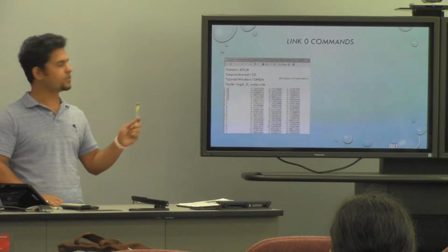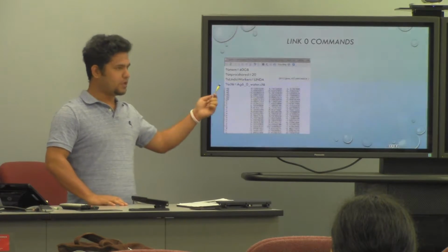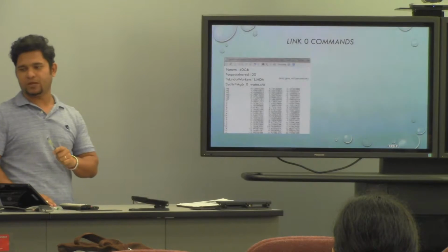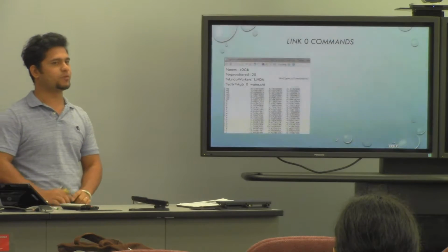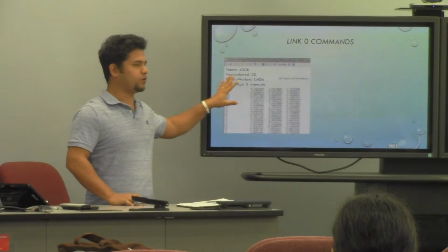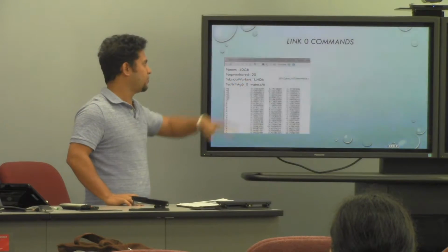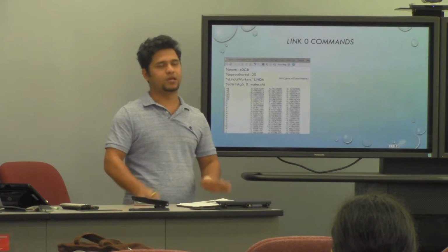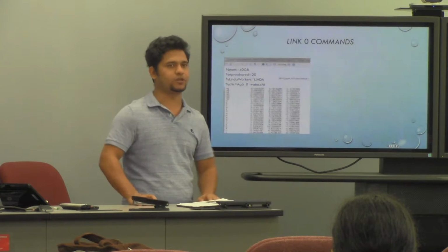The first section starts with the % sign. This % sign means this is the first section. It includes the mem command, which means how much memory you want. With this command, the software will ask for 40 GB of RAM. The next one is the number of processors, because some clusters have a default number of processors, but in our system we can use a different number.